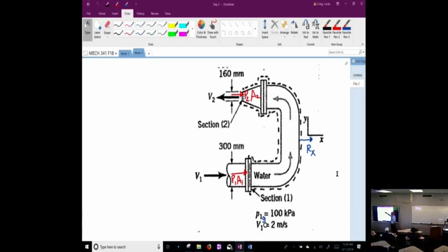Going out, it's only in the X direction. So technically, the only reaction force in the Y would be the weight of the water in the tank. That's it. But if this now shot at an angle, then it would, right? Yep, then you'd have to worry about it. Like a lot of fire hydrants, they have it at an angle, so you have to figure out all the components of it.